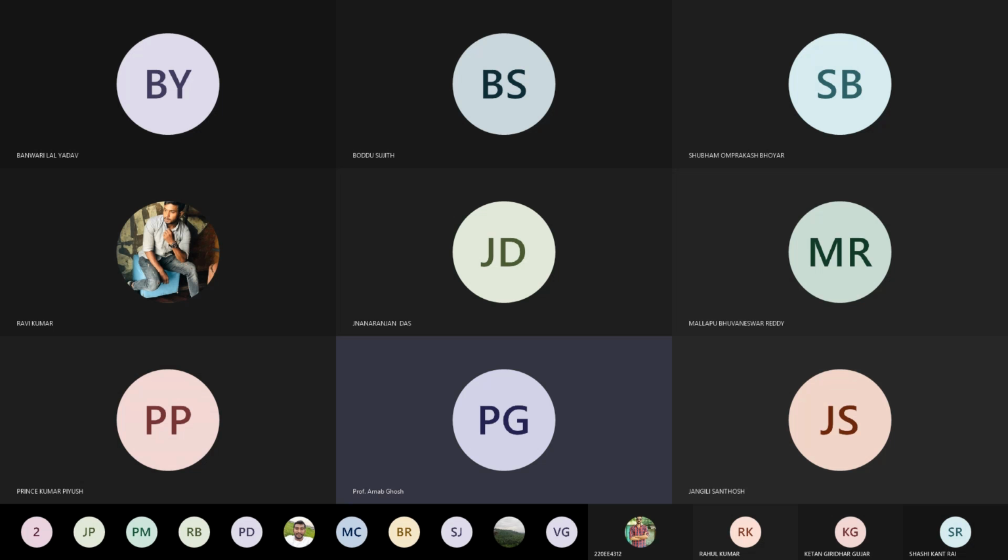One pole at the origin, cascaded with lead controllers. So two lead controllers are there, cascaded with each other. Here you can see that omega z1 and omega z2 both have distinct values, so they are not situated in a single position. In my later slide I have assumed that both of the poles are situated in the same place and both of the zeros are also placed at the same locations.